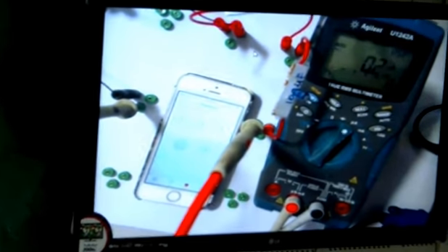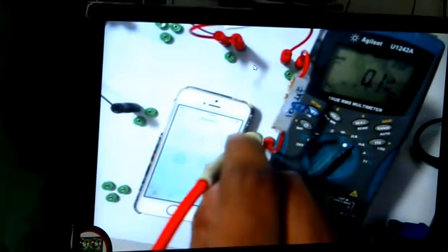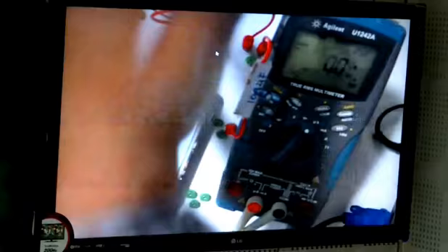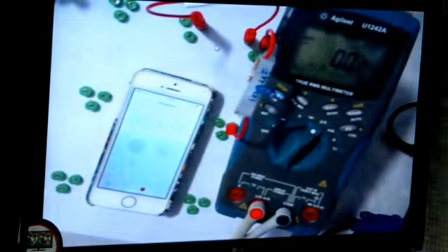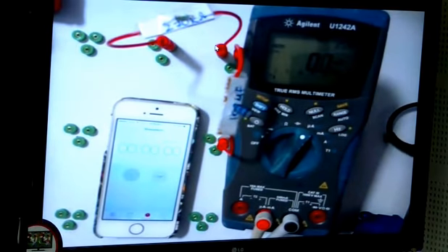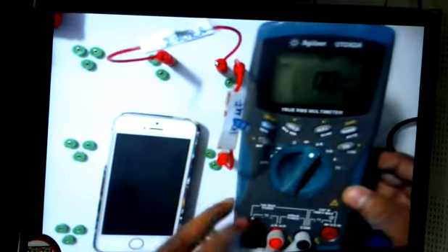So what I'll do now is I'll disconnect and remove the ammeter so the current becomes 0, and then I'll also remove the voltage source. So there is no voltage in the picture. Only two things on the board, one is R and one is C, but be careful, the C is already charged to a very high voltage of 6 volts. Maybe quickly we'll measure the voltage.